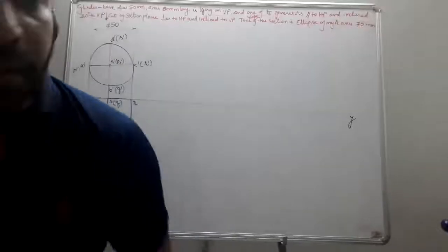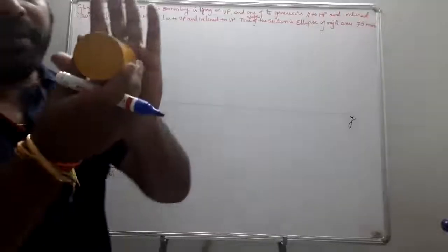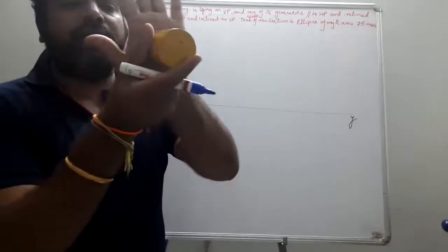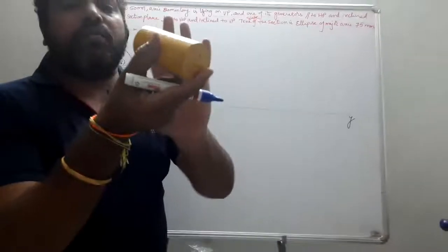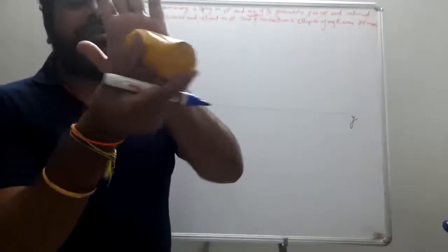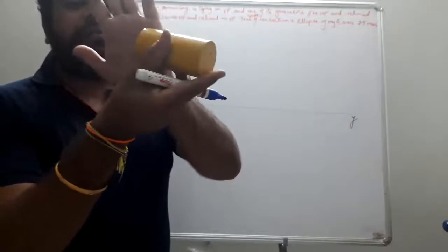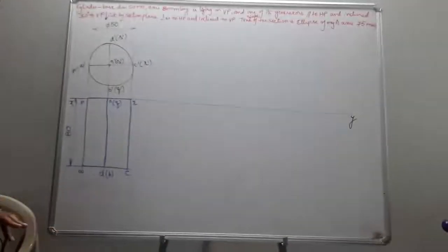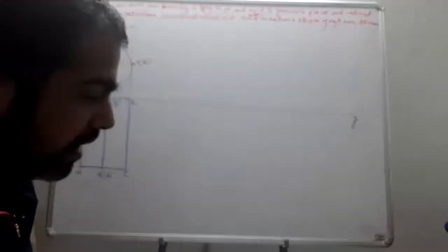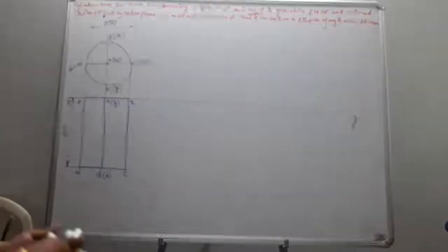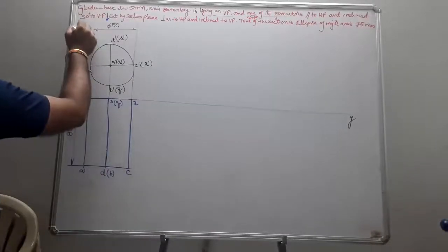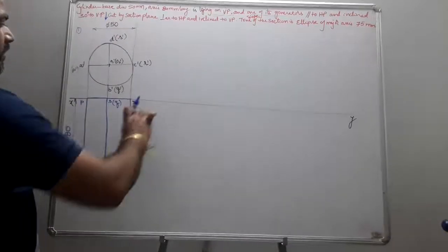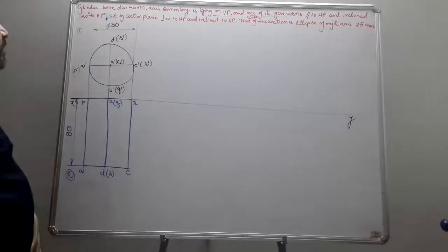That means one of the points of the base is going to be touching VP and it is going to be tilted for an angle of 30 degrees, such that you are supposed to draw your top view which is obtained. So this was your first step, this was your second step. It is to be tilted for the given inclination. What is that inclination? Which is 30 degrees.